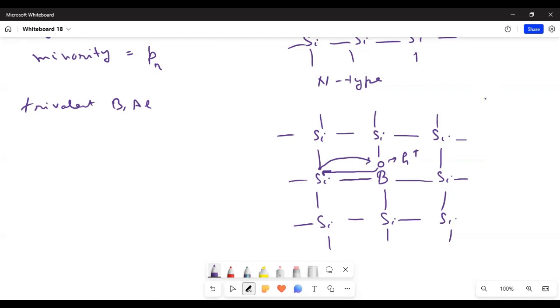The hole current moves in the opposite direction of electrons. So now this will come to this side, and this will be filled, and this will now have come to this side. So it is actually the movement of holes. In that case, this type of material is called p-type, and the charge carrier concentration is called acceptor concentration. Earlier it was Nd, now it is Na.